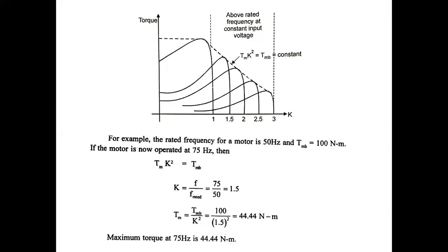This is an undesirable operation for the induction motor, for control above the rated frequency. In some applications like blowers, fans, and some underwater installations, specifically they require high frequency operation. There only we follow this high frequency operation. For the remaining cases, due to a lot of disadvantages associated with this technique, we mostly do not suggest this method of speed control for the induction motor.